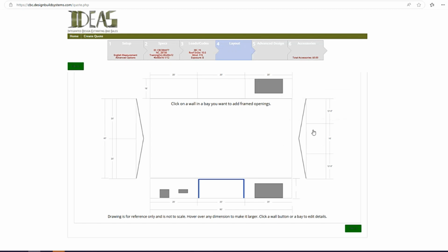So I've left the right end wall the same. If I don't do anything to the right end wall, it's going to default to the spacing as shown, and it's going to be a bearing frame. So that will be a cold form frame. If we switch to a half load or a full load frame, then your material is going to switch over to either a built up or a hot roll member based on design.